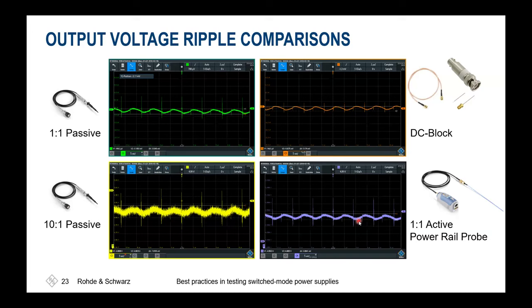And if you think about this increased integration density, you'll have more or less in every device nowadays a Bluetooth, wireless LAN, LTE, 5G modem, what else inside? And for being able to see these different bands and their relation and coupling on the power rails itself, it's very helpful to have this bandwidth. Otherwise, you wouldn't be able to characterize if there's a crosstalk or not. And you might see these high frequency components that could easily propagate through a rail to your system on chip, and then cause there a watchdog saying, oh, I'm out of spec here and I'd like to reboot. And this might be caused by this unattenuated propagation inside the system.